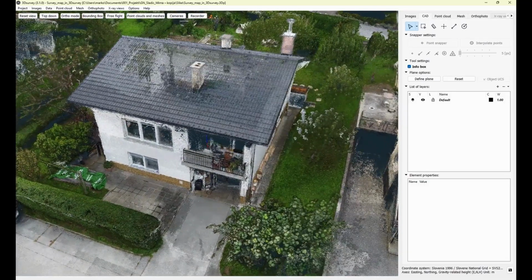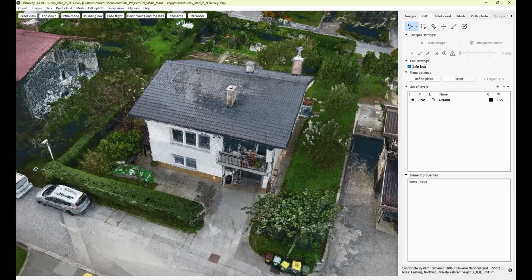Okay, cool. So here we have a complete layer system, a CAD engine inside. We can create a new layer, change names, set colors and thickness, make a layer active, and so on. But my suggestion is as follows. If you are always extracting the same layers from photogrammetry data for survey map generation, there is a good option to prepare a layer system the first time.